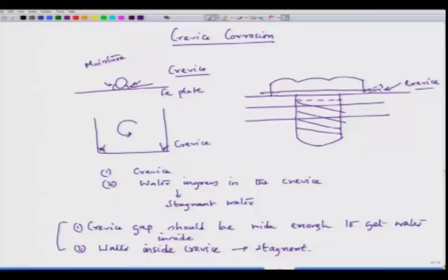That means there could be a small gap forming, and that corrosion point can progress towards the depth direction. So, if this is the thickness of the wall, at times this wall can be punctured and there could be leakage. This is the level of crevice corrosion that is possible. Here also there could be crevice corrosion around this region.